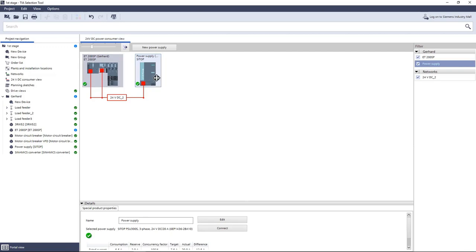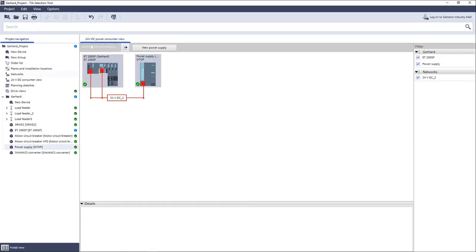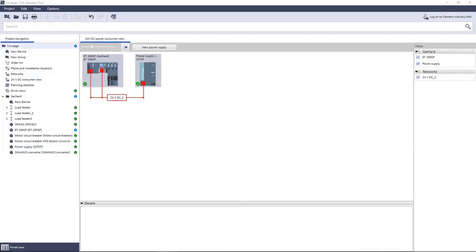So basically we will have a 3-phase AC power supply because we have a 400 volts incoming. We wanted to have a DIN rail mounting with a screw type terminal, and for example we can take this one of 20 amps directly here. We select the desired power supply and we can easily connect it now as a result, and we go down here, apply the selection and it's been applied, and you see that everything that was marked with an X before, now it's already dimensioned.